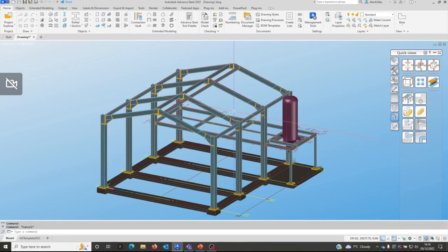The last caveat I'll give you to any of that: when you first fire up Advanced Steel, the first item you have to hover over is a beam. So after I fired it up, open a model, I'd immediately go to a beam and hover, so I get the rollover tooltip pop up. Otherwise, if I hover over a plate or a special part, the first thing I do, it breaks the rollover tooltips, and none of them will work properly for the rest of that session. You have to close and restart Advanced Steel.